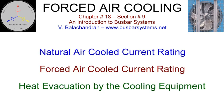A forced air-cooled bus also has a natural air-cooled rating. The ratio of natural to forced air-cooled rating depends upon the quantum of heat evacuated by the cooling equipment. There is no specific value to the ratio.